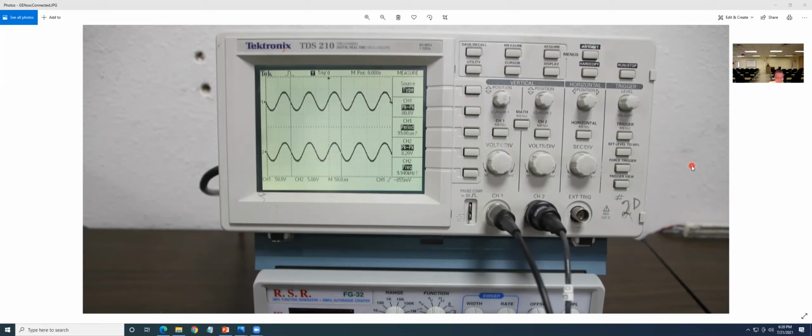Okay, any questions? I'm asking you again, one more. When the signal is not good, looks like this one, but it keeps running, it doesn't stop for you to measure or do anything, what can you do? Trigger. You can see in here, there is the trigger right here, level trigger. You can turn it to the left or to the right. That will stop the running of the signal.